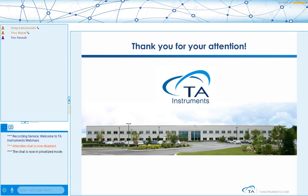Sure. And the way that we obtain molecular weight distribution from doing rheological testing is we have to do frequency sweeps. And one thing that's important is ideally we would get to the terminal region where the G prime is heading toward 0. It has a slope of 2. And you would also see that we are in the Newtonian region, in the low frequency region.